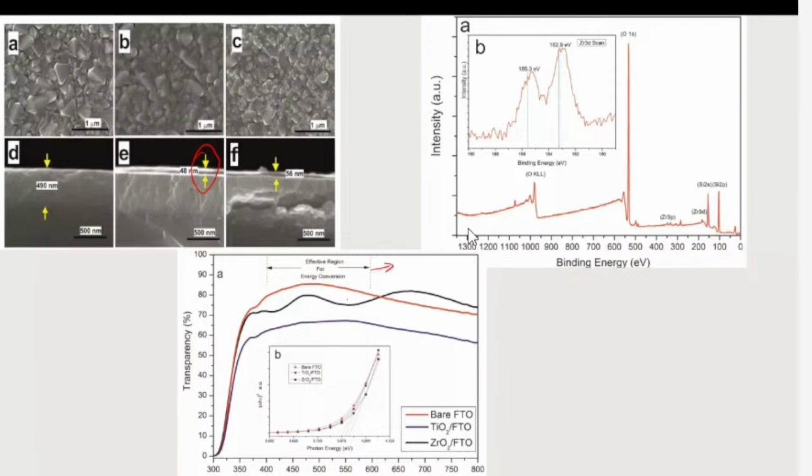For example, silicon cells show 25% efficiency at 1 square centimeter. But for a panel, the efficiency is less than that, close to 80 or less than 60 percent of it. It means that a lot of energy is lost by making panels from silicon cells. But in this structure, there is no loss like that. We obtained the same value for the 10 centimeter sample as for the 1 square centimeter sample.